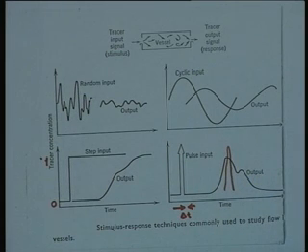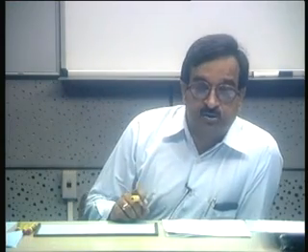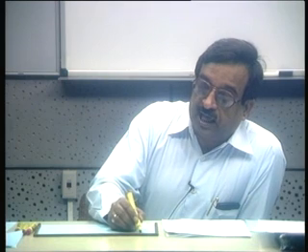And so now, although as I mentioned any kind of input can be given, for analytical convenience we often resort to either a step input or a pulse input, because with random signals the ultimate analytical solutions might be difficult. The step input or pulse input are the commonly used techniques for getting the residence time distribution for a given vessel. Now the response to a step input of the tracer is usually called an F curve.